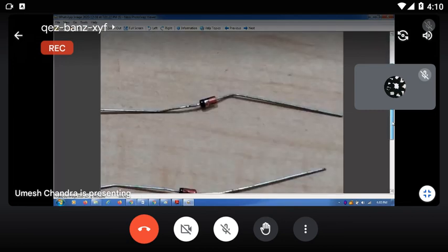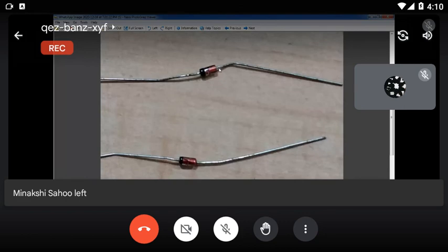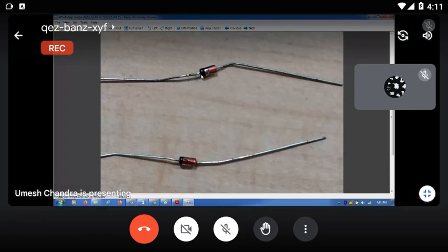Every Zener diode looks like a glass type, that is glass material. The black circle indicates the cathode, then the other side is anode, positive, and the black circle is negative. And it works in a reverse bias condition. And what is the function of the Zener? It is used for voltage regulation. Zener is used for voltage regulation.